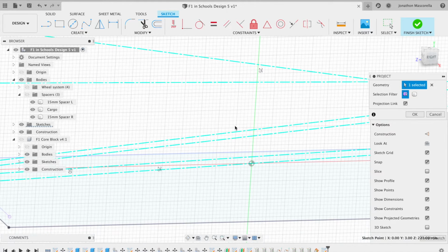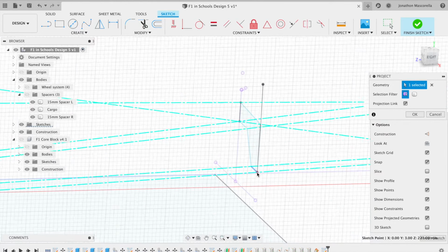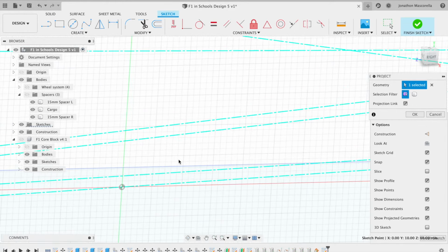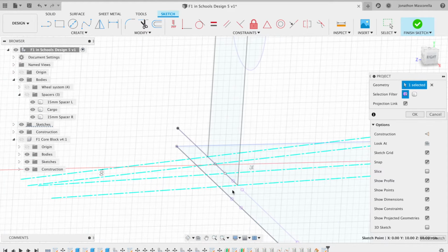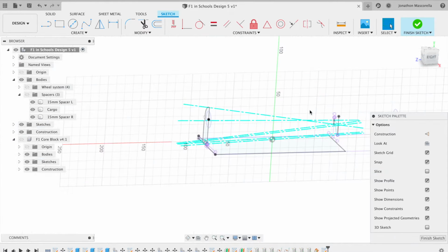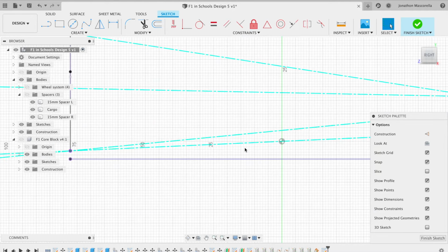It's easier to do it this way around rather than trying to put the planes at angle on and then draw the sketch at the end on all different planes, because eventually you'll run out of visual aspect of the car. So I'm going to project the beginning and end point of the sketch into where the axis runs between the 2 points of the front and back sketch.